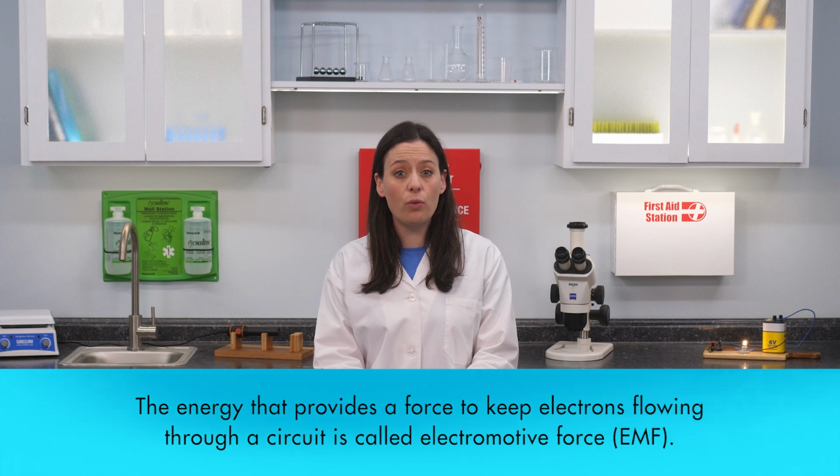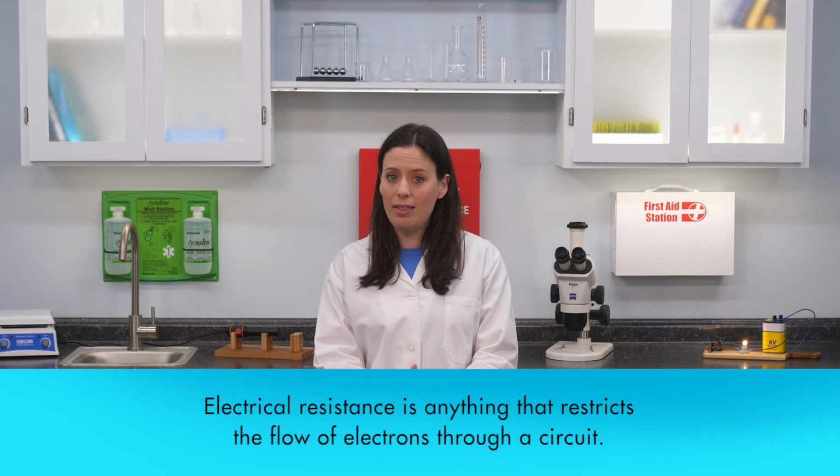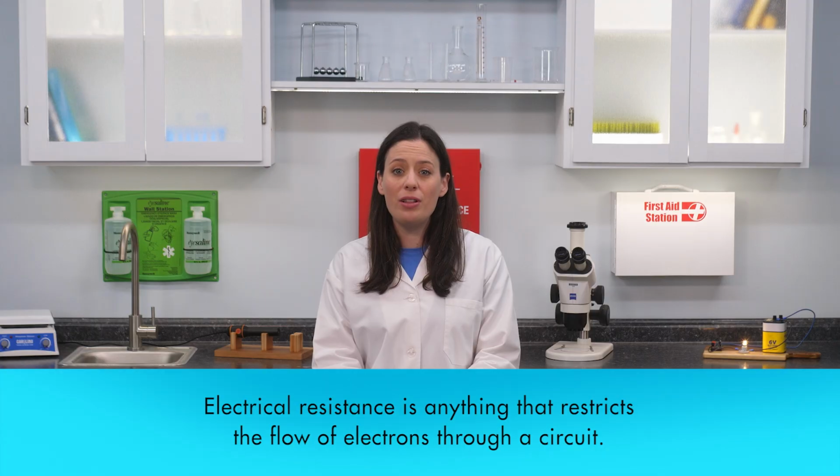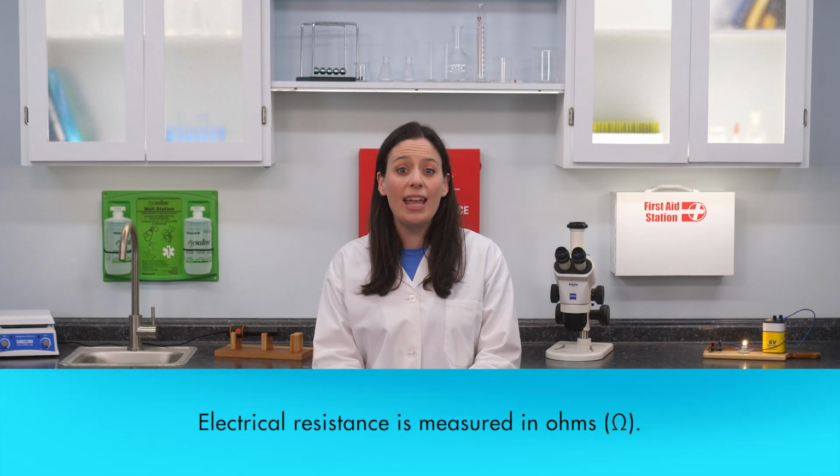Electric current will not flow unless it has a force to push it through a circuit. The energy that provides a force to keep electrons flowing through a circuit is called electromotive force, or EMF. EMF is measured in volts. Anything that restricts the flow of electrons through a circuit is called electrical resistance. Electrical resistance is measured in ohms.